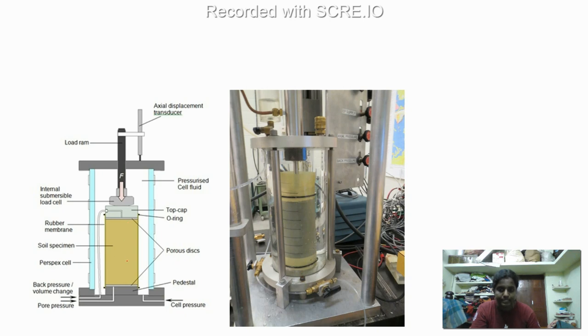There is a decrease in thickness. This we call the consolidation stage. Now, once the consolidation is over, when you are applying a load, that we call the shearing stage. Once you are applying a load here, you can see here.